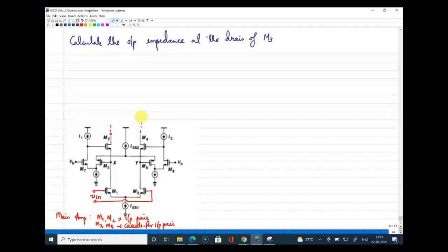At this time we will also identify that M5 and M7 are some auxiliary, and we will forget about the auxiliary part now. So what is the main amplifier now? Any response? You have input amplifier? Yes, it is telescopic. So how telescopic? You have an input device, you have a cascode for the input, and the rest if you elaborate or complete this structure.